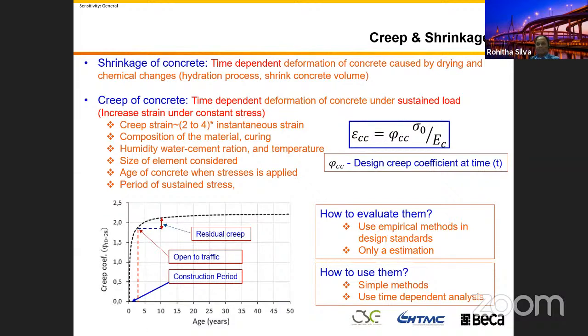That's quite significant. And creep in concrete depends on a lot of parameters. Some of them are the material composition, your concrete mix design. Like most of you know, in the olden days, concrete was constructed using 1:2:4, 1:1.5:3, so different kinds of mix design, 1:3:6, all these mixes, and then you put in water and cement, mix using shovels, and then pour the concrete.